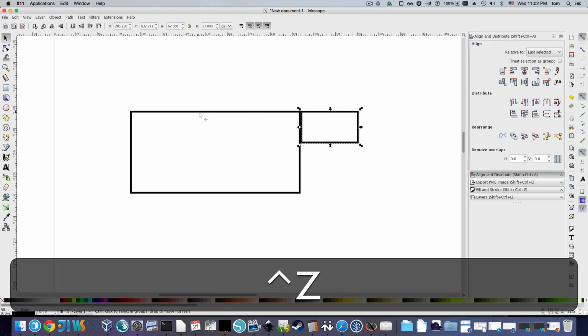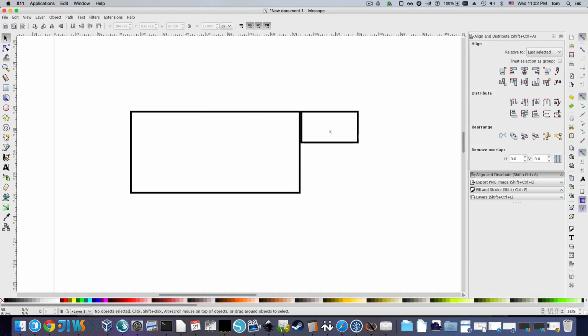So it is taking that into account, which is kind of a problem when you start doing the measurements that we'll do in a little bit. So keep that in mind. It's much better, if we were going to do something like this, to over-measure another box and then align it to the top right of it, like this. So that will keep our measurements sound.